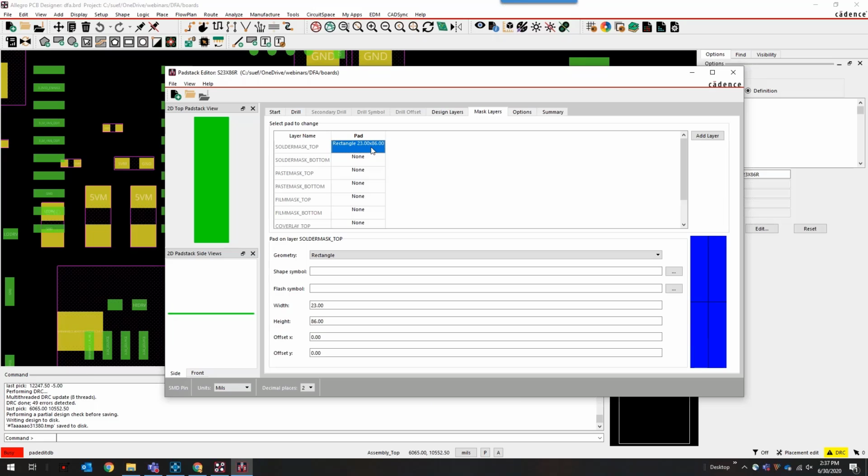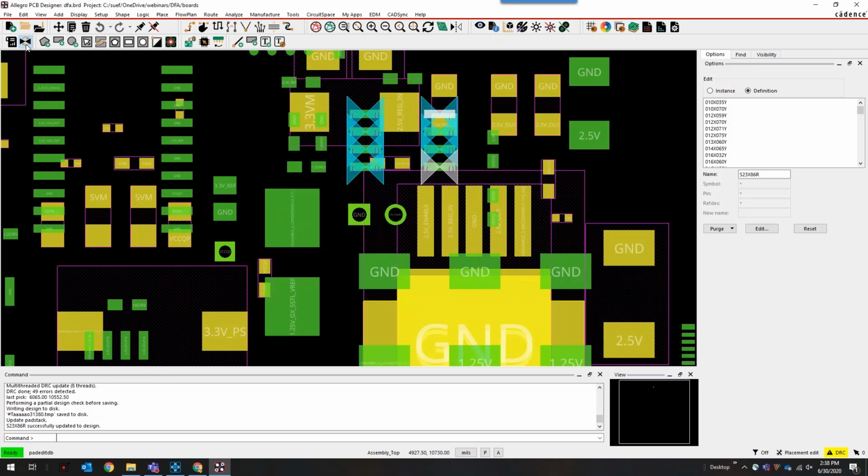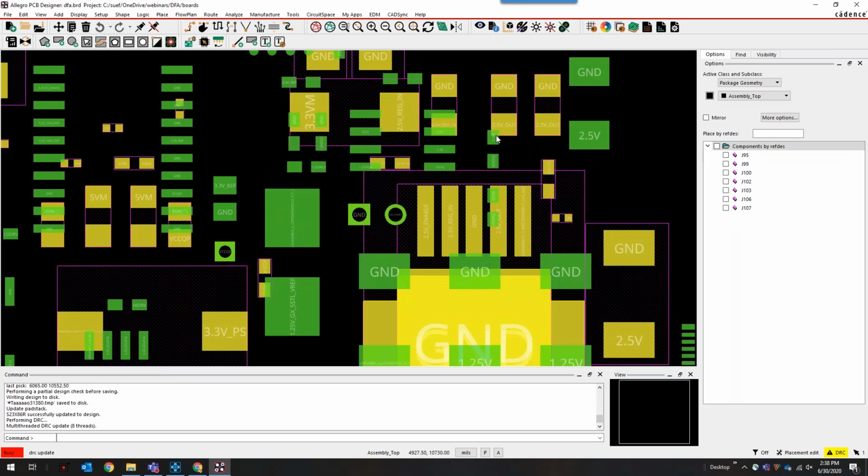And what I'm going to do is I'm just going to copy the solder mask, and then just push the change back into the board file and run the DRC, and now those are all gone. So now you have the paste mask in your design. It was easy enough to find it in the design, and you didn't have to worry about it going out afterwards and coming back so that you fix it after your design is complete.